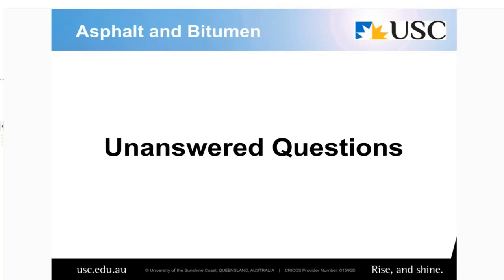But then you might put a rejuvenation or a preservation product on it after year 7 or 8, and that will significantly reduce your friction again. So it's changing all the time. It's changing seasonally, it's changing as the asphalt surface ages, it's changing as rubber builds up and then you remove it, or after you treat it with a rejuvenation product.